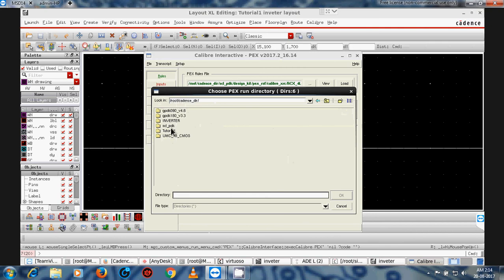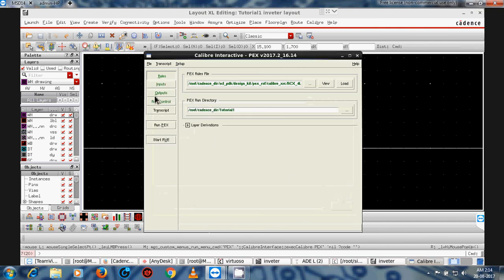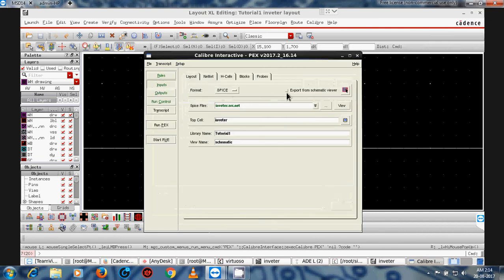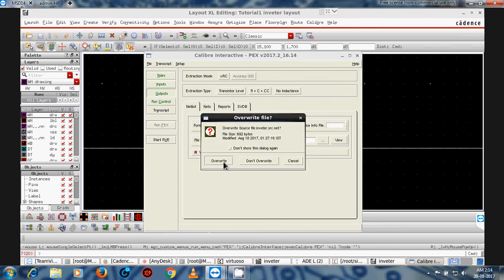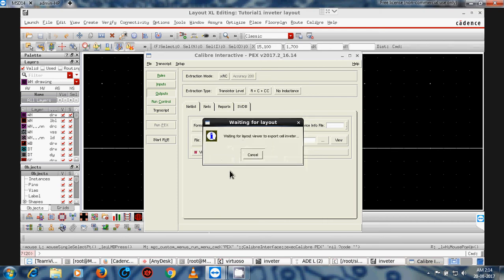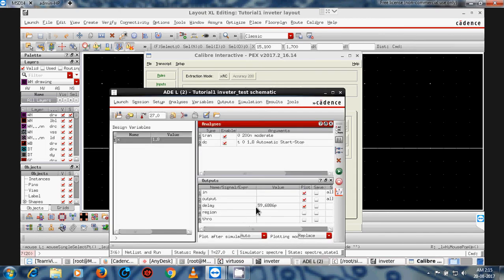I have already told you how to run DRC, LVS and parasitic extraction. So I am again running PEX to show you how to do post layout simulation with PEX running. You can watch here, this delay is 59.6886. After running the post layout simulation, this value will change.